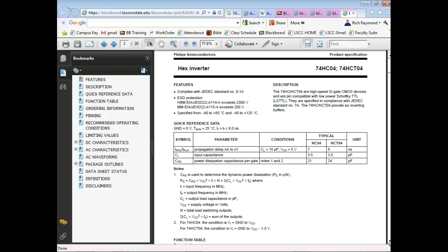These are CMOS. For years and years, if you saw 7400, it meant it was TTL. So we had a 7400 series and we had a 4000 series. The 4000 series was CMOS, and the 7400 series was TTL. And the two were not compatible with each other. So you couldn't use a CMOS chip to drive a TTL gate, and you couldn't use a TTL gate to drive a CMOS chip or gate. So you had to go through what they call a level converter, a special chip that would do that for you.